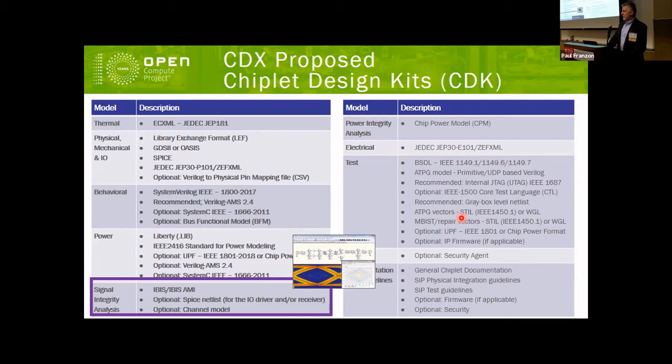So one thing that might be nice is a sample channel model can be provided by the chiplet vendors, although that wouldn't be for direct use, but it may be helpful in setting up their signal integrity setups for the system level application. Now, in the spirit of executable models, Touchstone models can be provided to define insertion loss, return loss, and that type of information. And eye diagrams also generally are provided in paper form, but it is possible to capture those in XML. So that might be helpful just to help with some automation in some of the analysis flows.